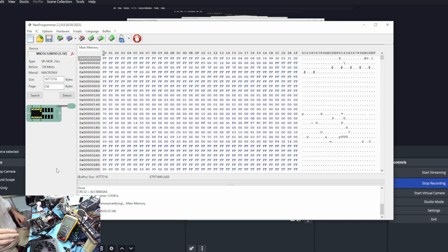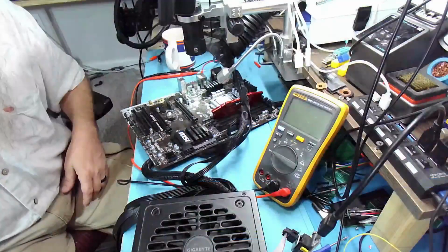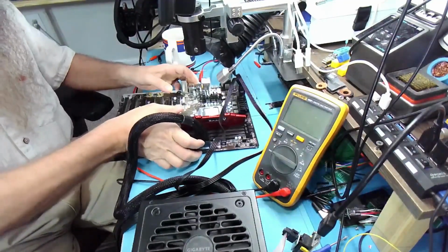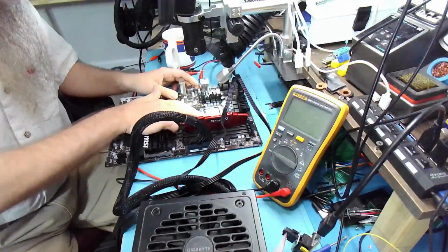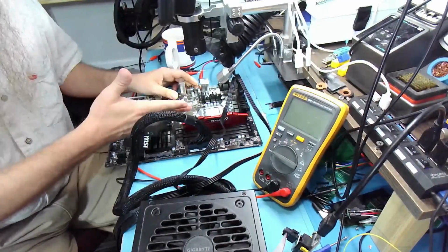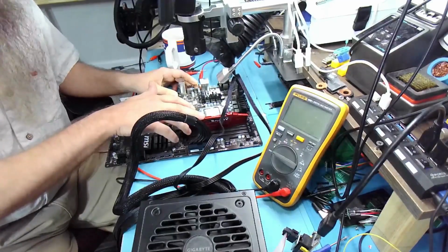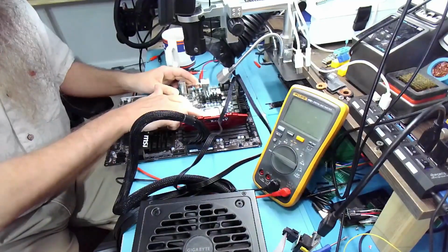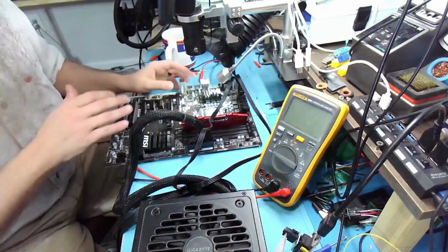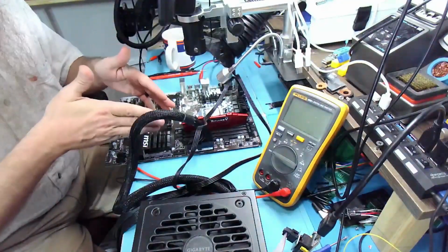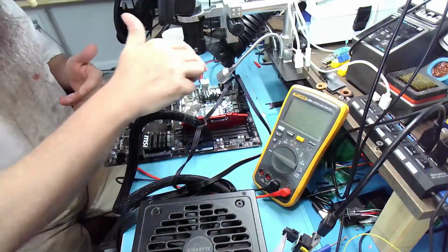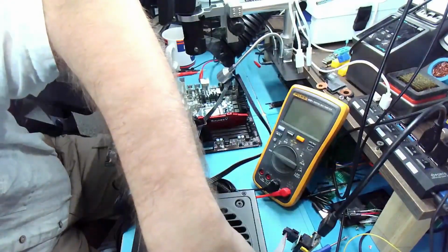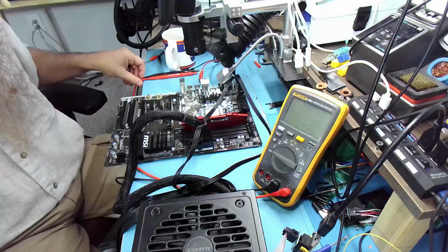So now the question is, is there going to be a difference? It's 50-50, because it still could be the CPU. Because SIO, I assume, that is crucial for the peripherals, right? So if the SIO or VIO is shorted on the CPU, that would explain why we can't connect to the memory despite voltage being correct. Let's start it up and let's see if it's gonna explode.